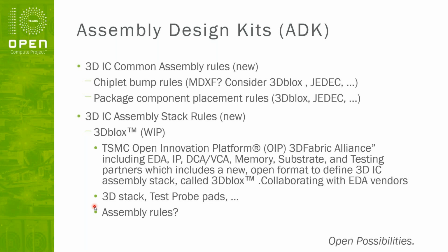So we do plan on supporting that, but there are other potential competing standards, and if this doesn't work out, we may want to consider another alternative. But right now, I think we do want to adopt 3D blocks. So this format captures the stack, how all the components are placed, whether they're flipped, where the pins are, and all that information. Stuff that would not be in your normal GDS LEF/DEF formats. They have a ProPad extension, so they are looking to add a lot of different things into 3D blocks. And assembly rules is something that is not supported in 3D blocks.